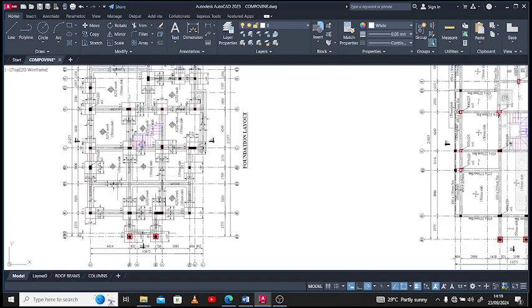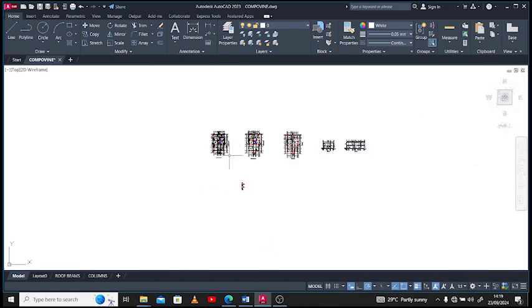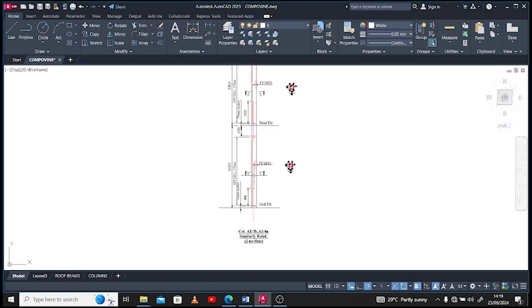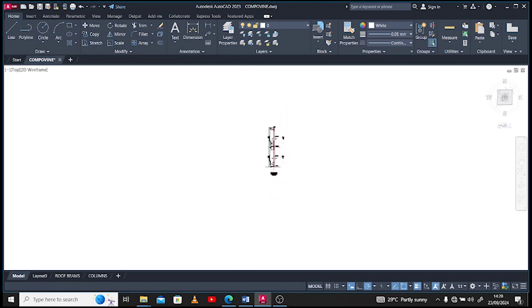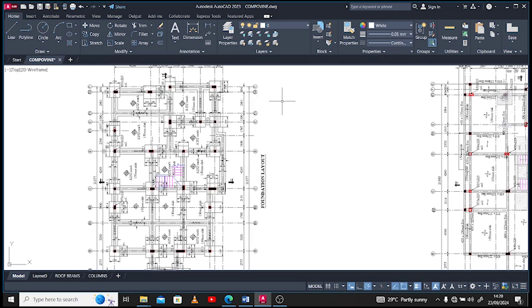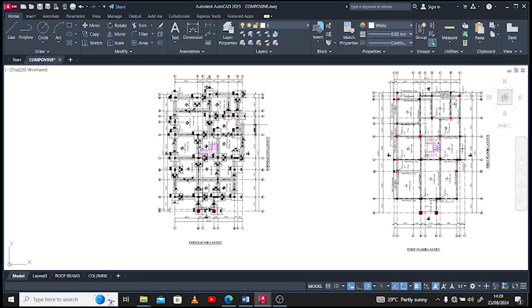To go about doing a column elevation and then the column detailing, before you can have something like this, which exactly represents a column detail for a structure like that in request, you ought to first understand that you need to come up with a column elevation that shows exactly what the column looks like. Then you can go ahead to place your reinforcement accordingly. And as you know before now, the way we do it is we use the standard method of detailing, so that you can get accustomed with the proper and the right foundation of detailing.